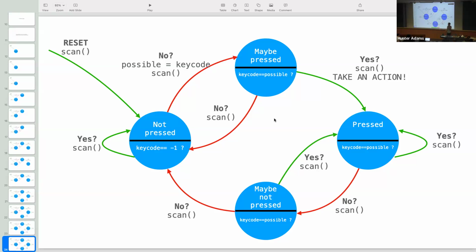And what I would recommend as a next step is change the interrupt service routine for the beep beep code very gently, and I'll show you how in just a moment, such that it doesn't automatically produce a new beep. And then move the logic that currently lives in the interrupt service routine that transitions it back to produce another beep, move that logic down to the keypad thread so that when you push a key, a beep comes out. So you go beep, beep, beep, beep. That's a great first step.